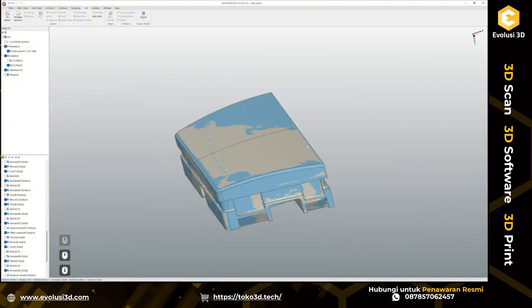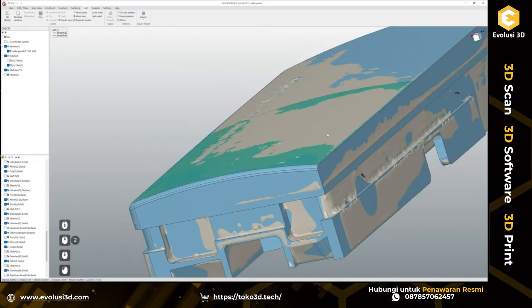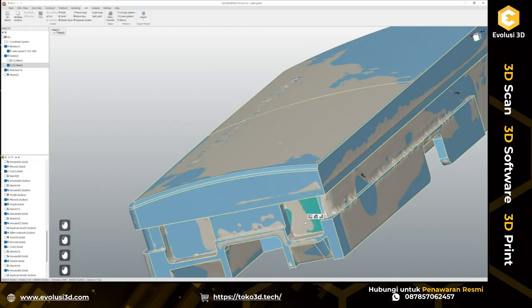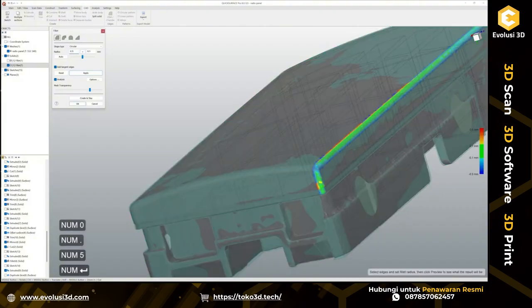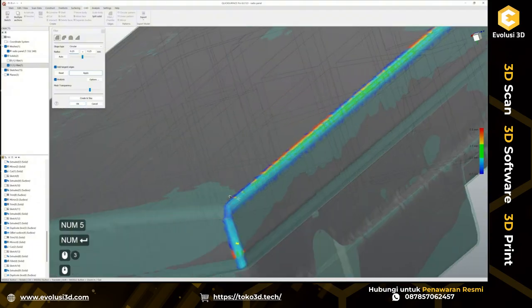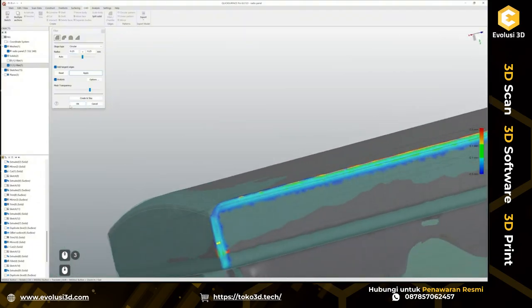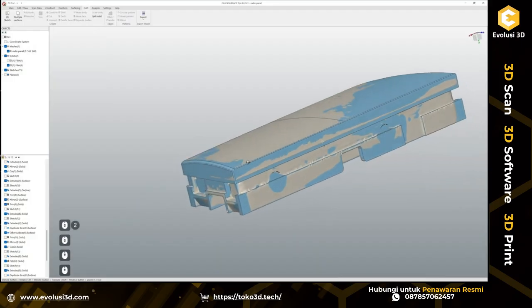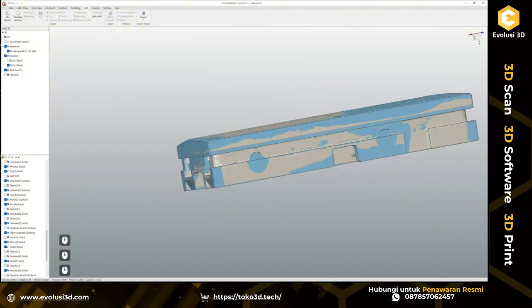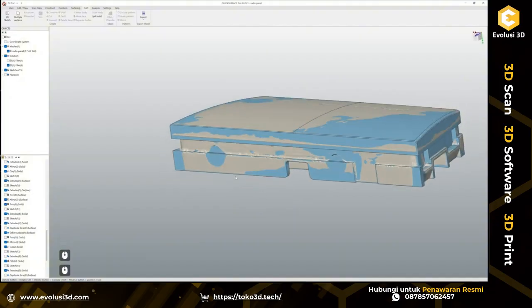Just not to make it a completely sharp corner. And so I can add fillet here of 0.5 millimeters. Also, no, this one looks way too much. Let's add it as 0.25 maybe. Because this edge is pretty sharp. Okay, so this looks good.